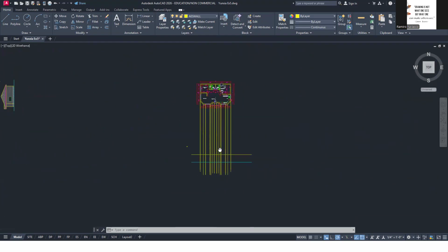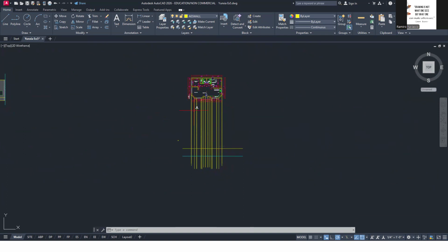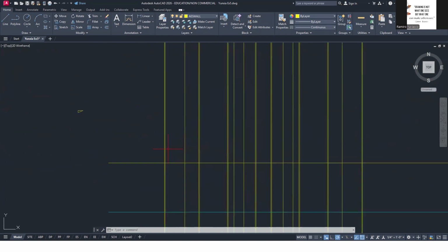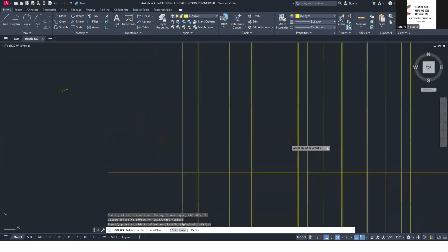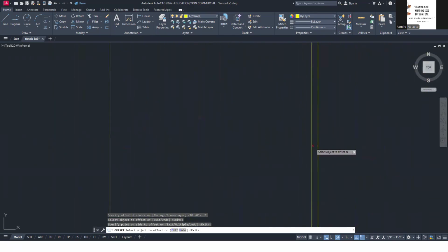I think we did a projection by how much? So our roof from the wall is either 2 feet. I don't know what you have. 2 feet? Yeah, okay. So I'll just offset this by 2 feet then. But if you have the wall, the roof, then you could have also copied that. But I'm just going to offset this by 2 feet right there.